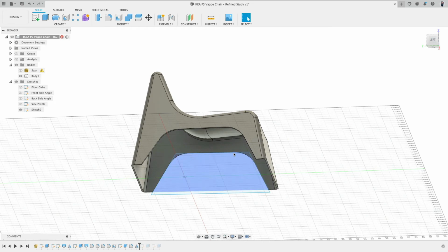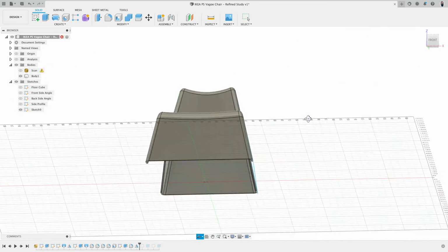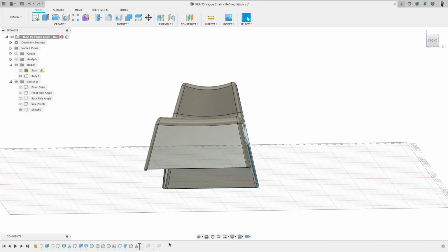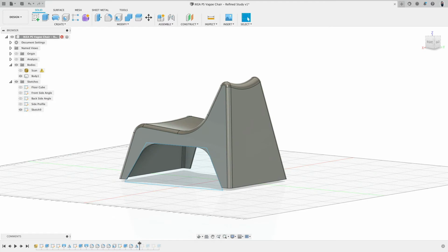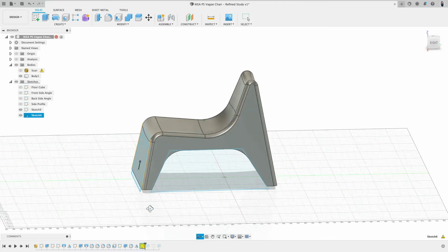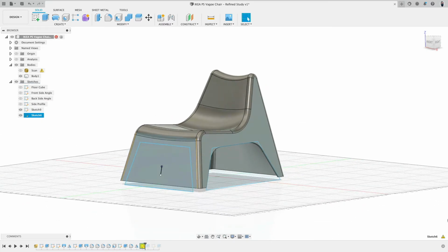Cool. So I only have to select one time the edge and fillet it, or 2 edges instead of 4 edges. It's a matter of preference. If you want to cut the front and the back, and then we fillet all the edges, or if we do this way.